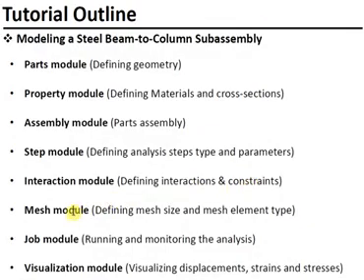And then finally, before you submit the model, you have to do the meshing module. This is where you define the mesh type, the mesh element type, and the size of the meshing, and the way your mesh looks. And then the actual job module. This is where you define your job, run it, and check the analysis steps while it's running to make sure that everything is correct, that you don't have any problems in the model. And finally, after you conclude your job, of course, there is the visualization module. This is where you visualize the output, look at displacement, strains, stress contours, plot some figures, or create some videos or take some pictures and so on.